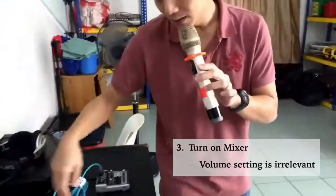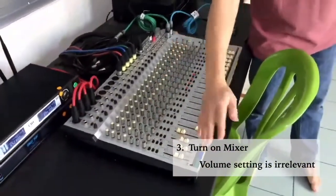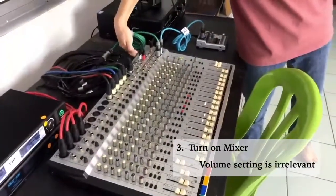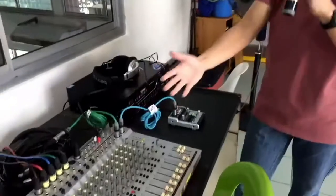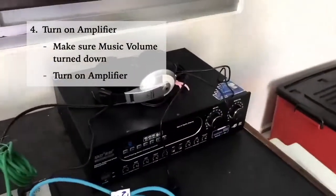It doesn't matter whether all these buttons are set at 0 or not. Actually, you can just leave it where it is because it doesn't matter at all. You just need to turn on the mixer. The speakers are not powered yet, so it doesn't matter, that's why. So after you turn on the mixer, then you come to the power amplifier. Last of all, you turn on the power amplifier, and how do you do that?